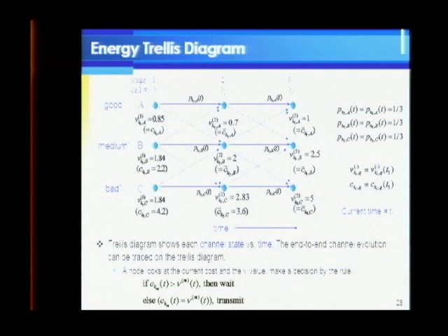That's right. Okay. So you assume that you have the same speed and the same rate of transmission no matter which cell you are in? That's right. So you don't consider that if you are near, you may have a larger bit rate? We don't. The kind of model that we have here is that, for example, you're using the same modem, a 100 kilobits per second modem, and that's a given. So we're not changing that. We're not doing rate-adaptive transmission here.